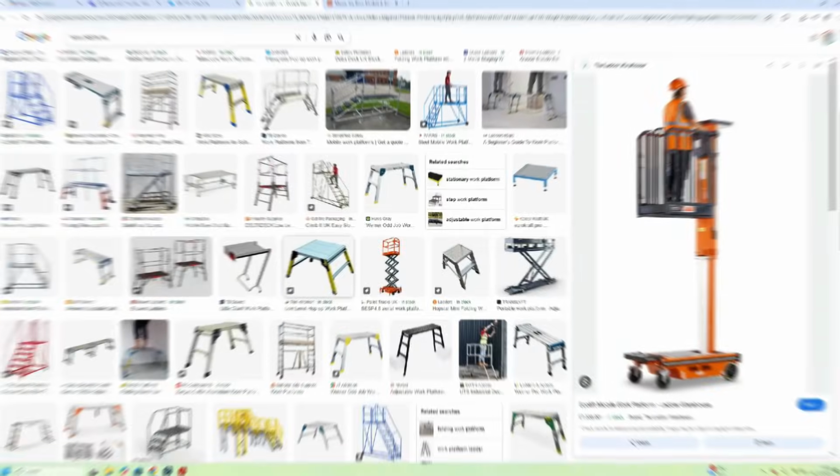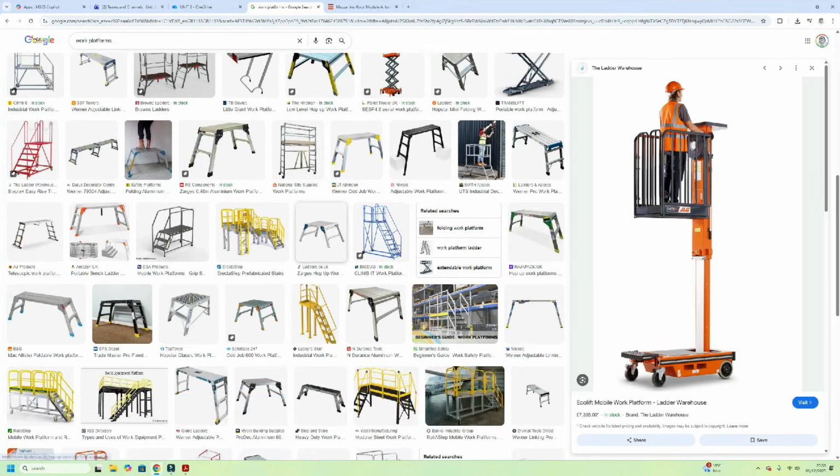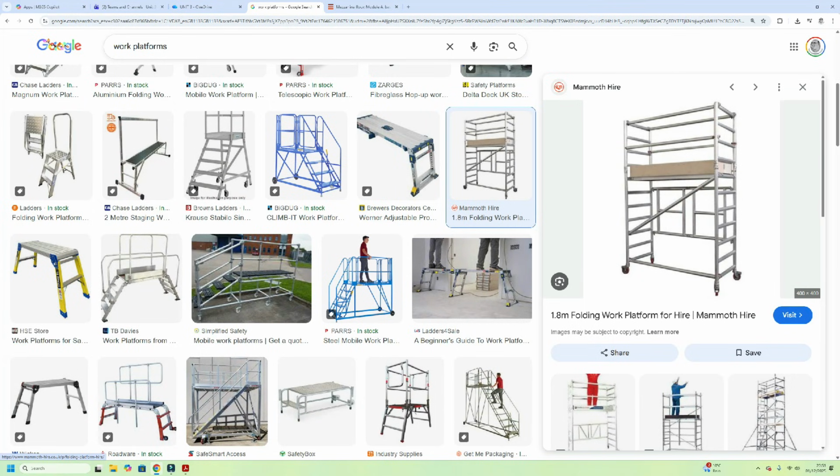Okay, what else we got? What else can we see here? These are work platforms. Now, can you see this board around the outside? There'll be a specific height from there to the platform that you want to work on. You've got this board around the outside. You've got these tubes in the middle. There'll be a certain height that you should have a minimum of. If you're hitting that, there'll be another bar in between, and it means that you have to crawl into that space to get on there. And these toe boards or vertical uprights, if you want to call them that, will help you feel for the edge of the platform. Okay, it's important that you feel for that.